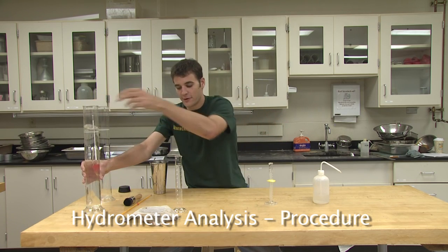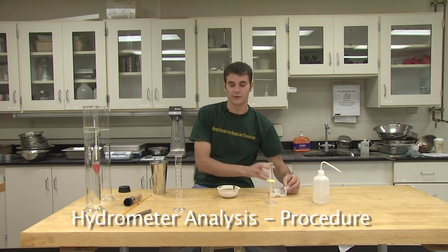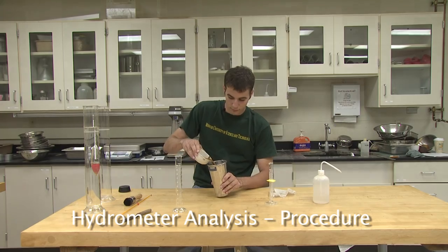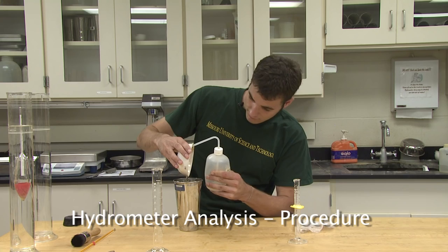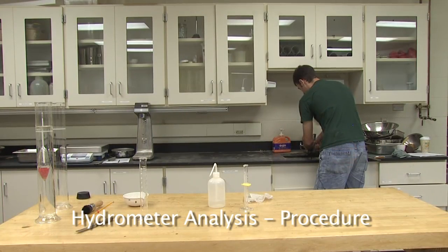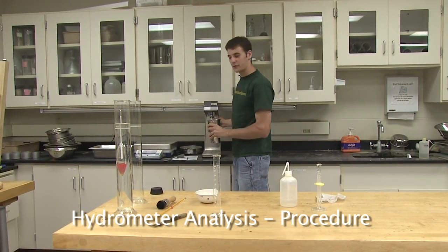After the 15-minute soaking period, transfer the sodium hexametaphosphate soil solution into a dispersion cup. Use a squirt bottle with water to ensure that all the material transfers out of the evaporation dish into the dispersion cup. Fill the dispersion cup with water until the water level is about halfway up the cup. Mix with a shake mixer for 2 minutes.